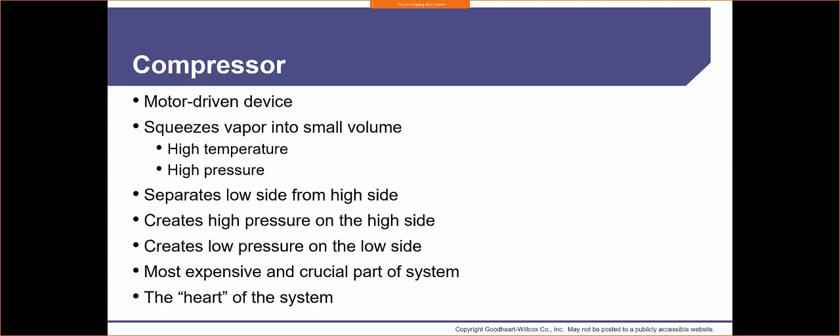I know I told you guys about this maybe a few weeks ago, but we want to make sure that there's no moisture in the system. The reason being is that we don't want that moisture mixing with the refrigerant oil. If it does, it starts to create an acid, and when we have an acid, it starts to eat away at the motor windings inside the compressor.